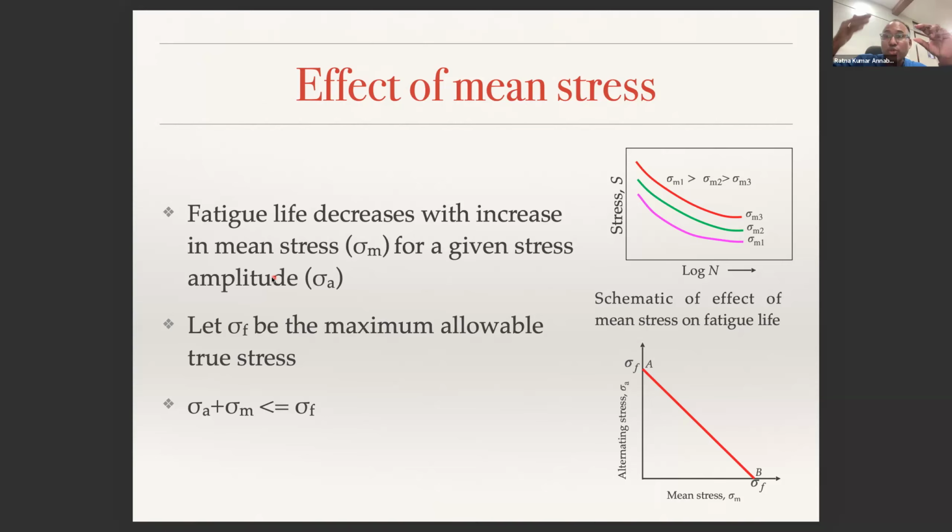If the mean stress is positive, that is, tensile in nature, it is detrimental to the component, because it adds fuel to a growing crack. As a result, the fatigue life decreases with an increase in mean stress for a given stress amplitude.